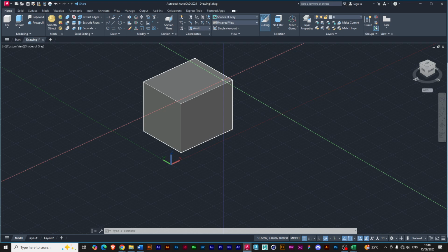This modeling is when you create a new file, you have to make sure your workspace is actually 3D, because in that view that you were in, there's no box there. It's line. So you have to change to 3D modeling. Even if you use a drawing template, sometimes you can still adjust the workspace. Because even if you did AutoCAD.dwt, the normal one, you can still change the workspace. So that one is like the default value.